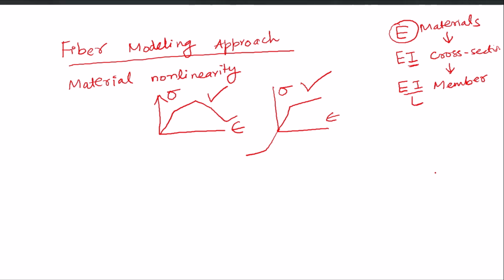In a nutshell, if I define a nonlinear model in contrast to a linear model, I will say that a nonlinear model is damage aware, which means it can tell you the structural damage after the analysis. It will not indefinitely follow F is equal to KU forever. Instead, it will tell you whether the applied loading has caused a particular damage in the model or whether the structure will be able to sustain that applied loading or not.